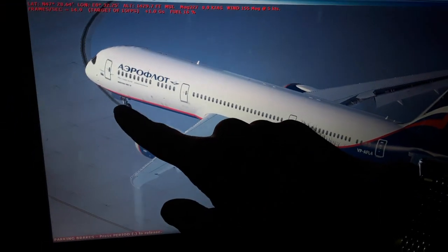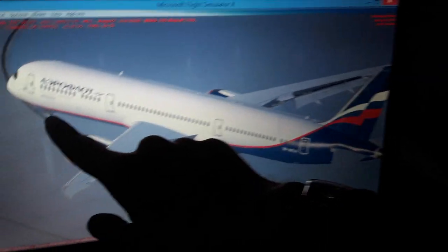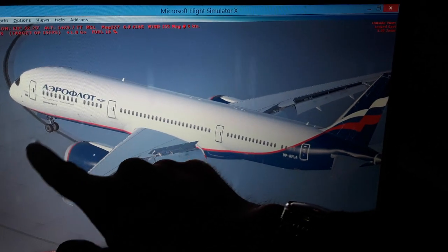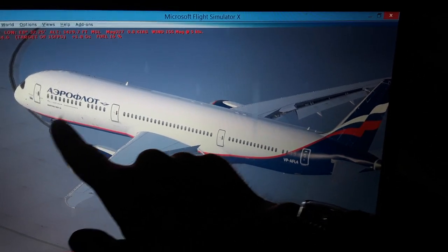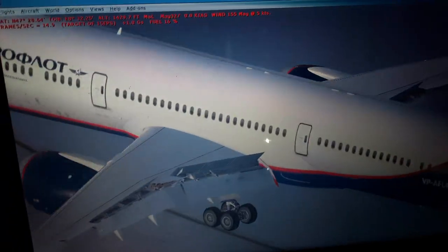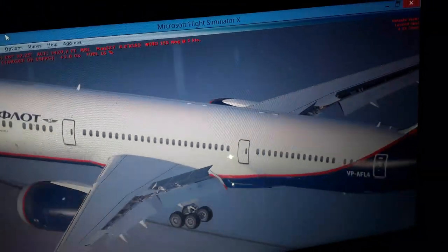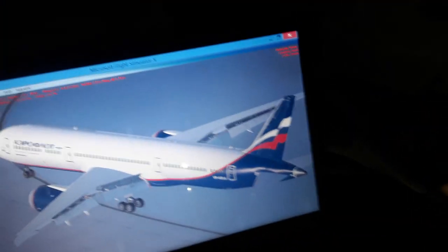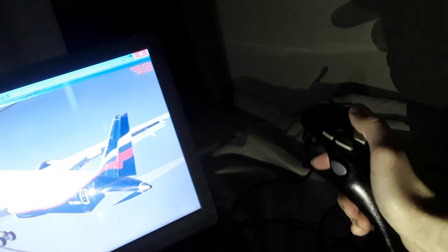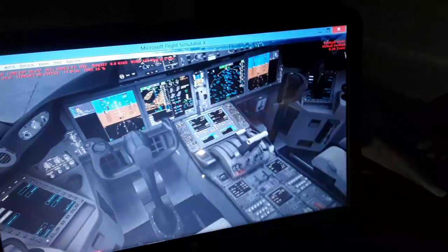From 0 airspeed up to 45 knots you have a deflection of 76 degrees either left and right, the forward nozzle, to make left and right turns using the forward nozzle steering over here from the rudder pedals again, from 0 to 45 knots.